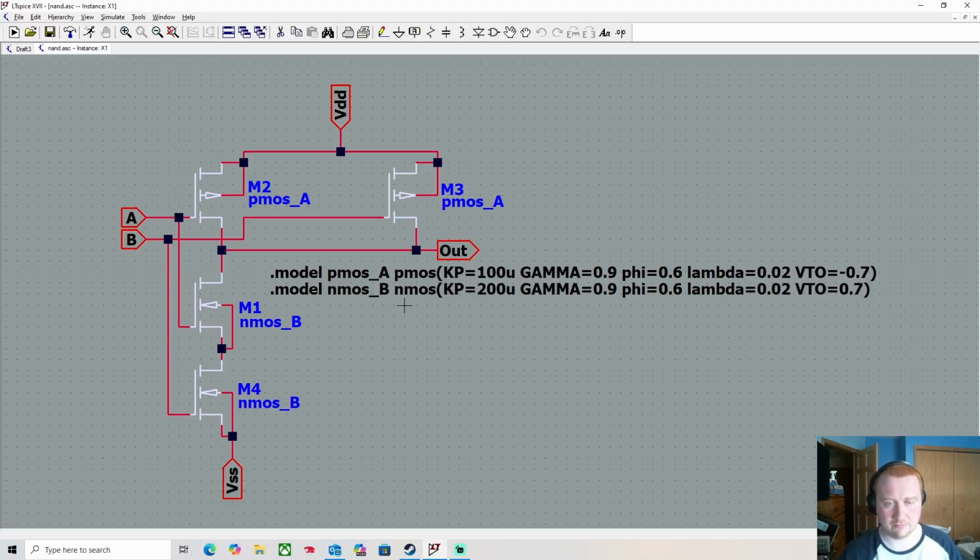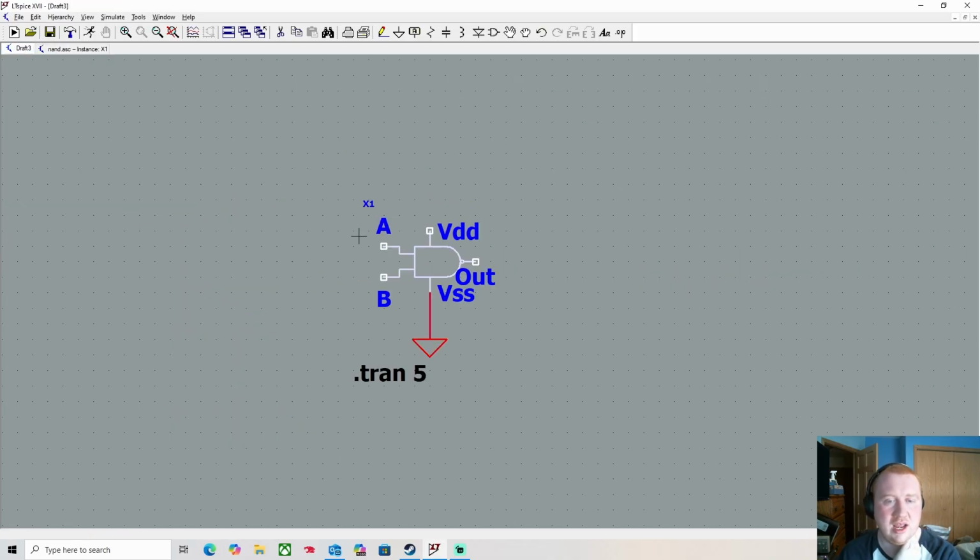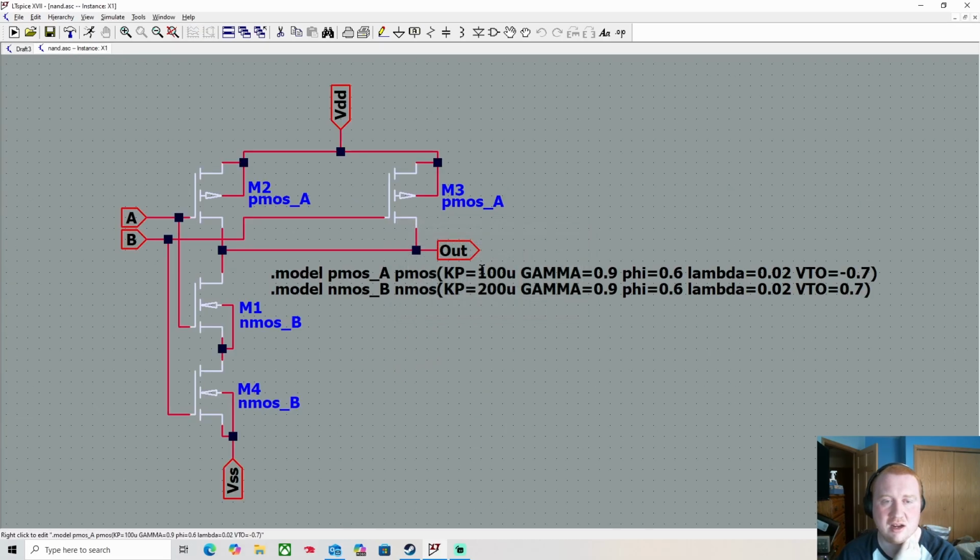I don't know, like I think I left this bottom one as a PMOS earlier and I was getting wrong values for my voltage readings. You could be like, hey, this isn't turning out quite right. Let's see what's wrong with the schematic. Then you go over the schematic by saying, let's look into there. We find the mistake, correct it. We can save right in this instance, and it will save the master file, and it will fix it right away. That's a benefit of doing it this way.